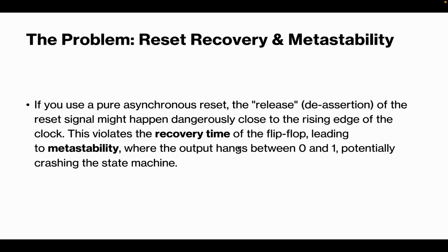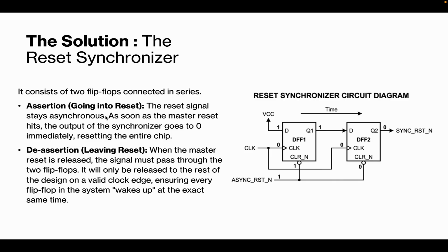It is confused whether it is 0 or 1, where the output hangs between 0 and 1, potentially crashing the state machine. The flip-flop will not work as intended. Since FPGAs have multiple flip-flops, one mechanism is the reset synchronizer, also called synchronized asynchronous reset.